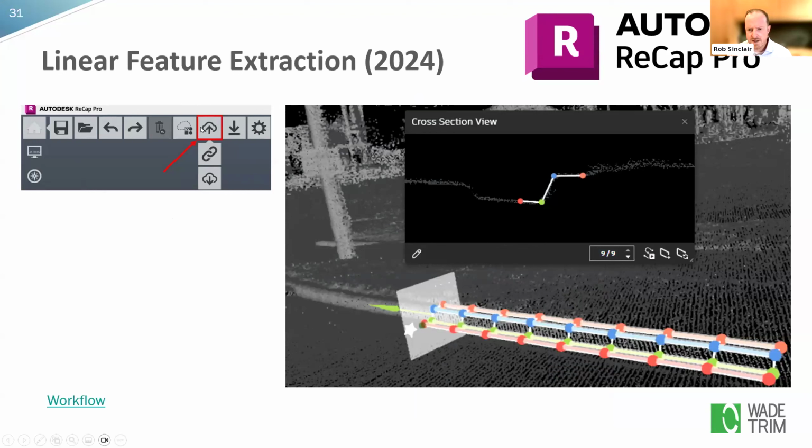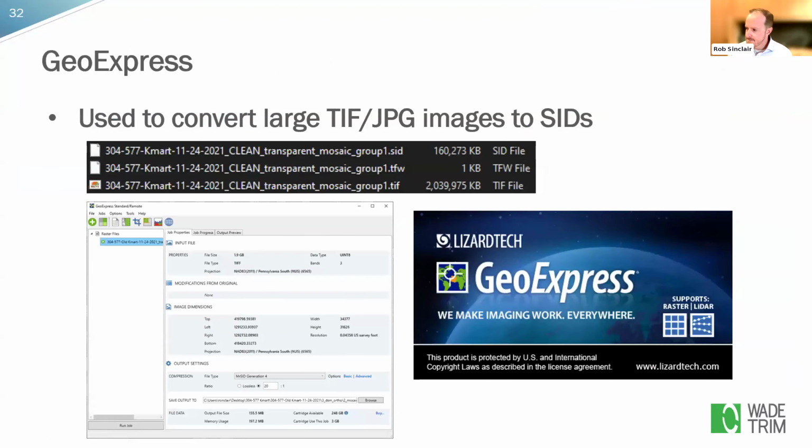You have to have a project set up in ACC, upload that point cloud, then you would go into the web interface and open that point cloud to get to this function. Basically this is great for extracting curb and gutter lines and maybe retaining walls and things like that. You could create a template and it will automatically push that template through, and then you can extract those lines as 3D polylines or feature lines to use in Civil 3D.